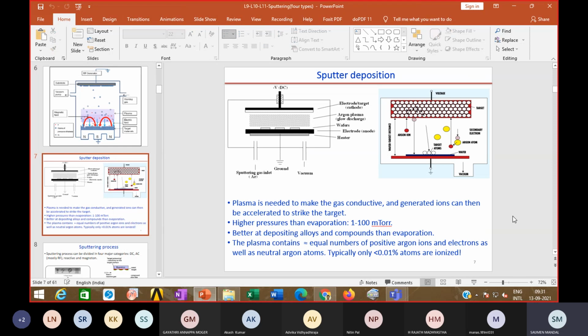So similar for alloy also, we have seen that in case of alloy, the composition keeps on changing. And that's why, suppose one particular composition you want to deposit in physical vapor deposition, if you use one single alloy target, that composition should be entirely different according to that calculation, or you have to use two different targets.